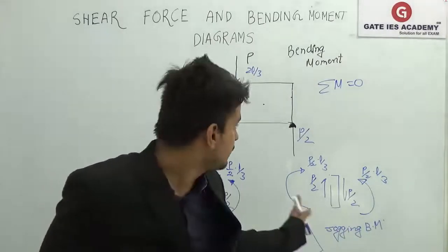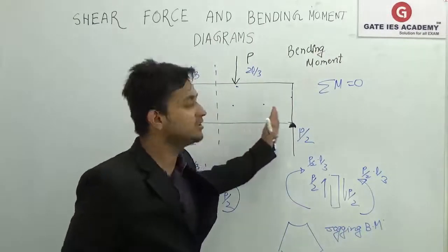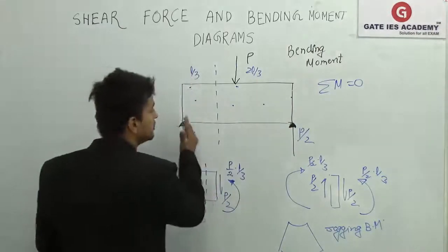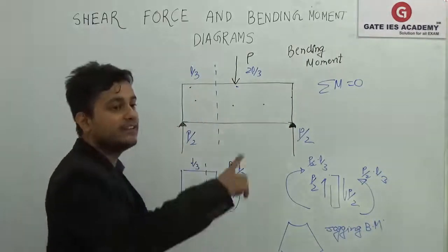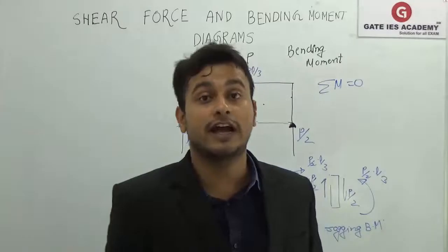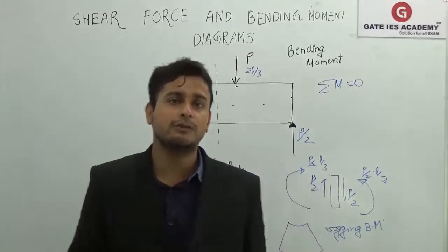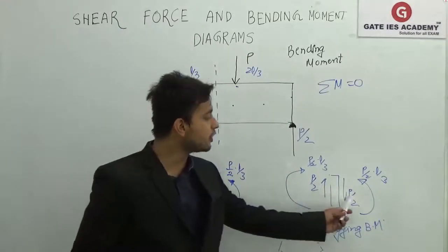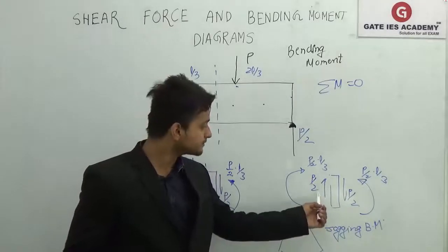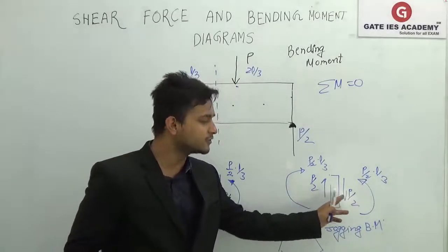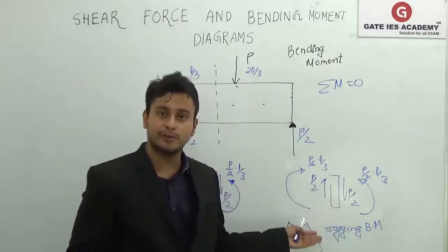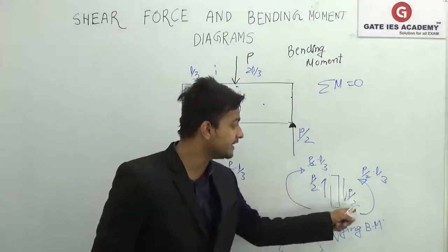So here, what we can do is calculate shears in all the sections, throughout, and then we can draw the shear force diagram for that. We know the shear force value at every particular section. Out of these two, what will you write down? Shear force. You do not say that net force on the system is 0. Obviously, it is in equilibrium, it will be 0. But shear force is taken as one of these.